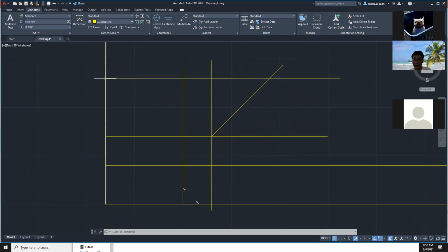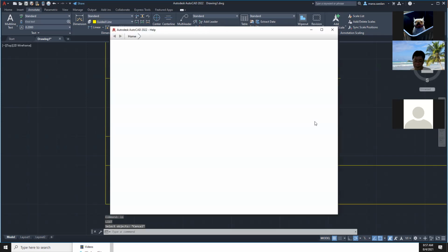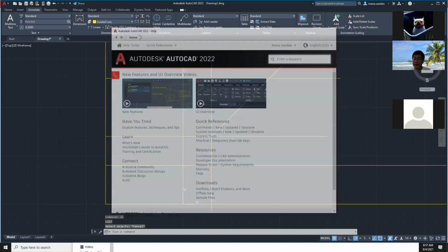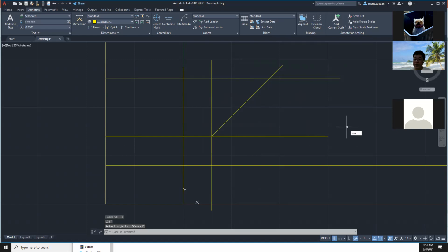The width here is the same width as here, and then we have the 45 projection line. So we touch the top line here. We can draw another line from there and then going down.